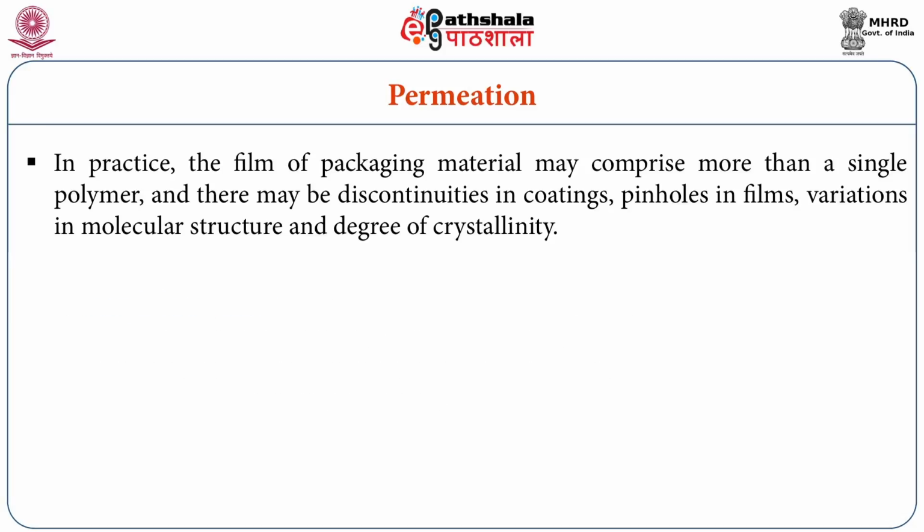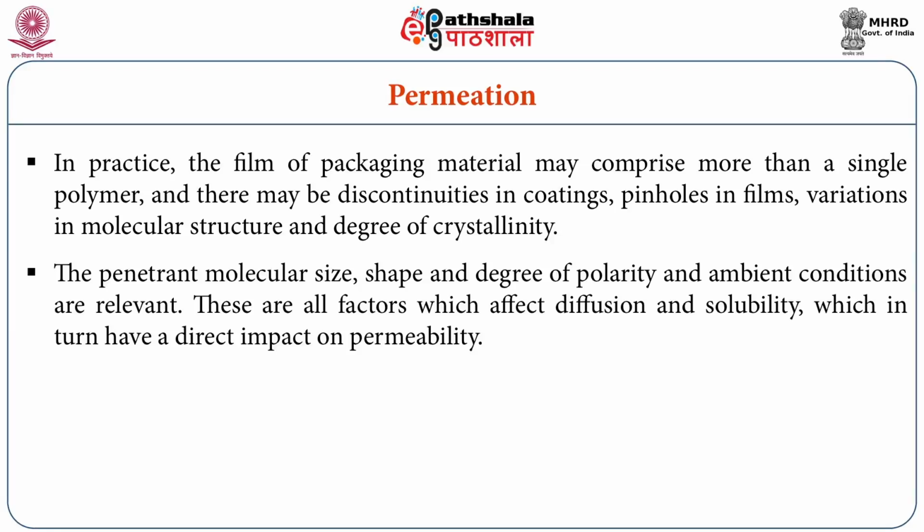In practice, the film of packaging material may comprise more than a single polymer, and there may be discontinuities in coatings, pinholes in films, variation in molecular structure and degree of crystallinity. The penetrant molecular size, shape and degree of polarity, and ambient conditions are relevant.